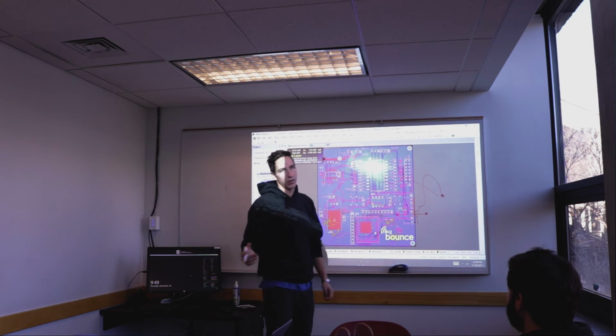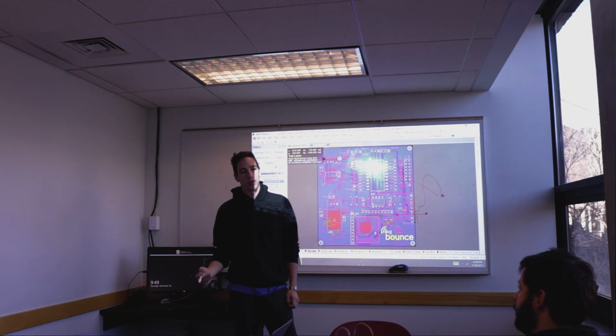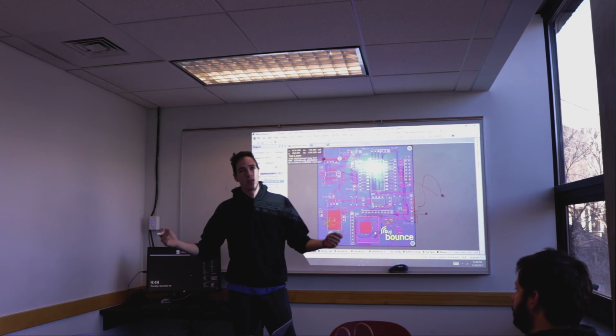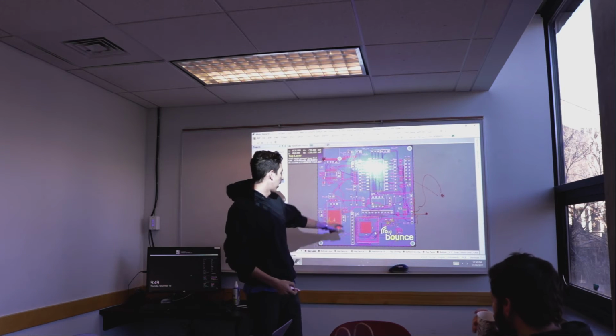And so that increases the resistance, and you're going to get voltage swings on your ground plane, which is never good, because then the IC doesn't know the threshold changes, and then you can get bit errors and everything like that.